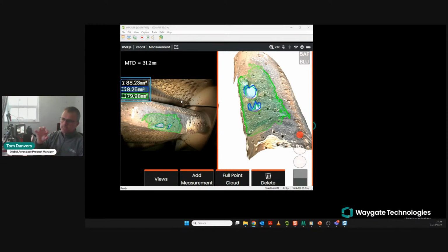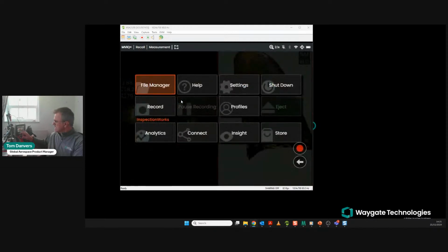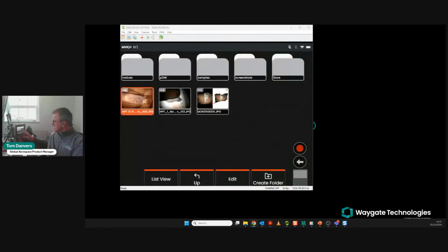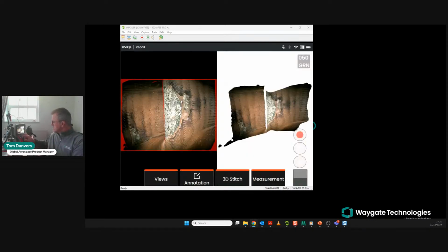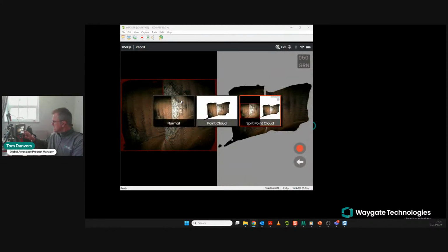If you were to do this exact same area measurement with the same, shall we say, perimeter with the traditional area measurement, you will get the same area result, rather than a different area result if we applied different logic. So just to make you aware that this is generating a best fit plane, just like the traditional area measurement. And let's just show you the process associated with